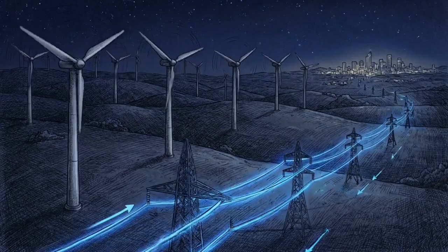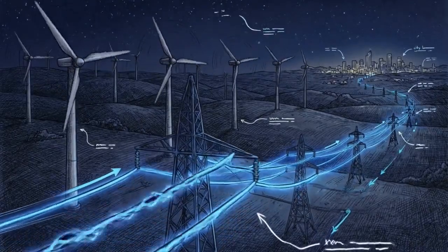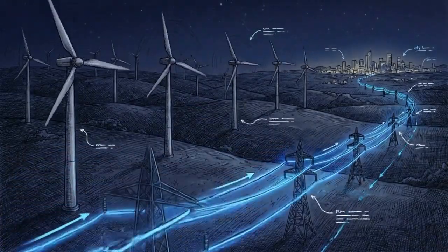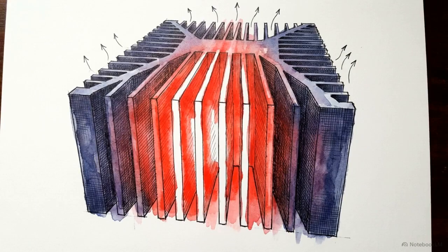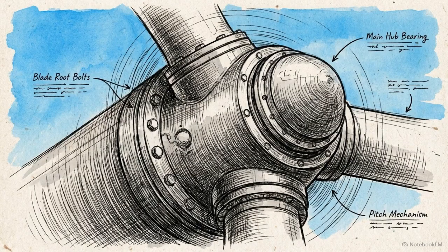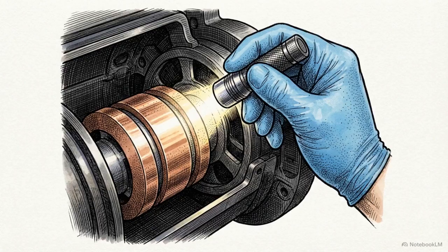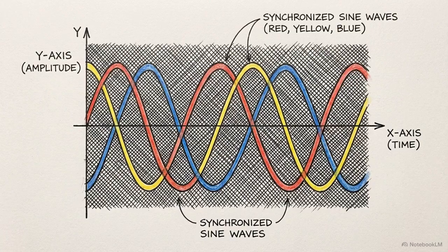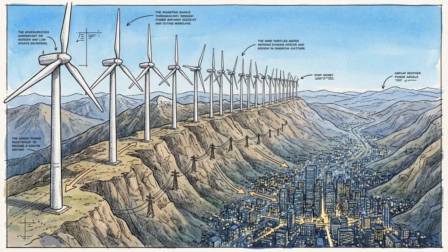When grid voltage drops, the DFIG's converter logic responds by providing the reactive power necessary to keep the regional grid synchronized. The heat generated during these high-speed power adjustments makes coolant flow and heat sink maintenance critical for long-term hardware survival. Reliable operation requires a combination of vibration analysis, slip ring inspections, and continuous monitoring of grid phase balance. Maintaining the precise operating parameters of the partial scale converter ensures stable power delivery and long-term hardware reliability.